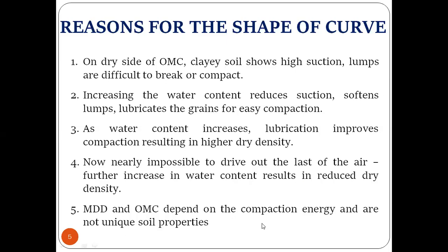MDD and OMC depend on the compaction energy and are not a unique soil property. MDD and OMC depend on how much compaction energy you are going to provide. Depending upon that, MDD and OMC will change, right? And they are not a unique soil property. It is not a particular property of this soil.